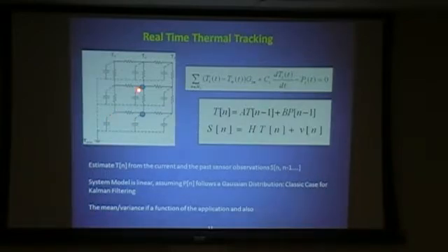So let us suppose you have sensors at a few of these locations which are being sampled at a certain rate, and you'd like to find at all times the value of the voltage, or the value of the thermal profile of the chip. Okay. So this has been formulated as a standard conventional state estimation problem, right?